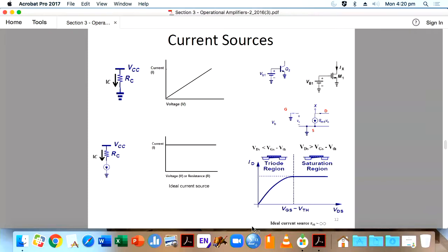If you take a square wave and take an FFT, you will get so many frequency components. If you remove some, what will happen? Then it will become like this. You know what I meant? In a square wave, if this is in the nanosecond range, it will become wider. But if it is in the millisecond range, you will not see widening here, but it will start going like this. In nanoseconds, you can see the change quickly. But if it is in milliseconds, you will see the change in these edges, because here it is very, very small.